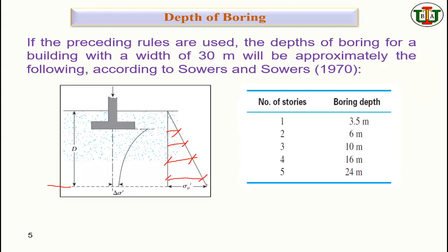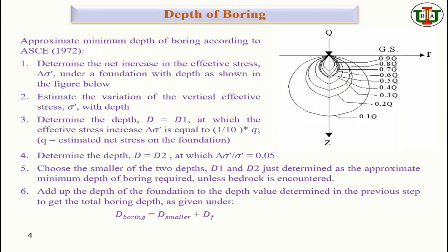And this is the difference in that layer, how much stress is increased with respect to the previous layer. Yes, sir. Okay, so now if we want to calculate the depth of boring, we need to know this information first: determine the net increase in effective stress.